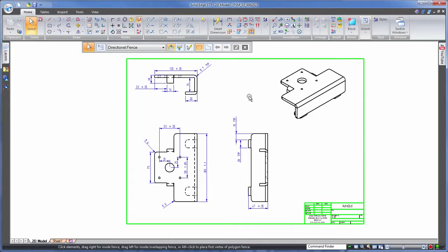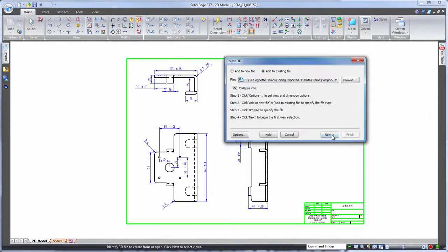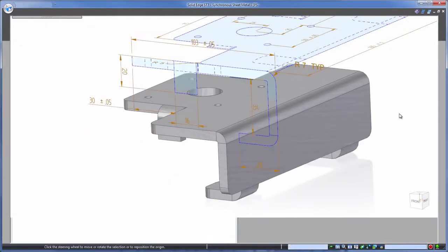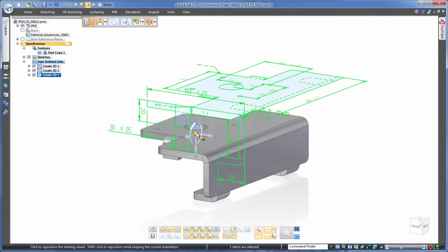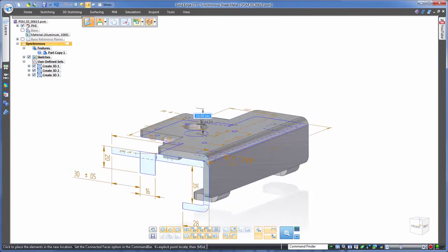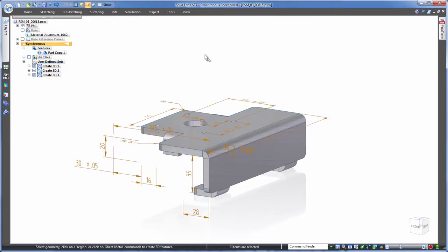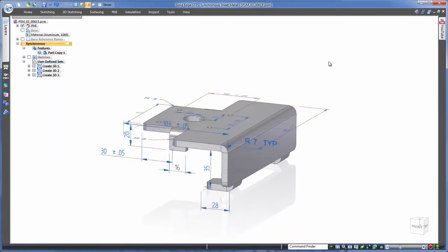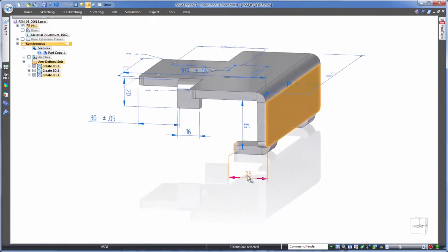Well, check this out. Once we open the DWG inside Solid Edge, we can use a simple tool to grab the information we want, just by fence selecting on screen, and then apply that information to our 3D model. Now you've already seen this steering wheel in action editing 3D geometry, and to keep things consistent, it can also be used for things like this, snapping drawing views into position over the model. So, nice to see the manufacturing intent overlaid in 3D, but wouldn't it be useful if we could control the model with these dimensions? Well, Synchronous Technology in Solid Edge can do just that. A simple click to attach, and these dimensions are now live, enabling us to make the required changes that we need whilst maintaining this manufacturing intent.